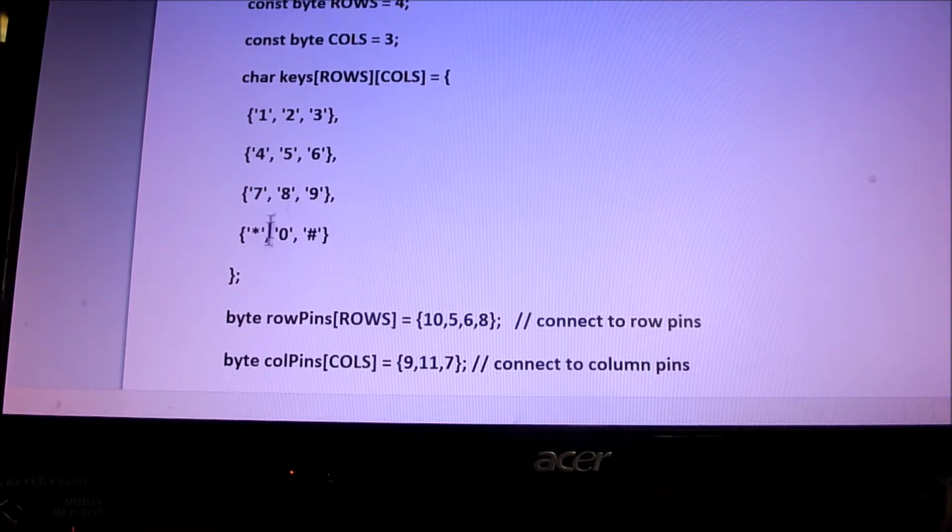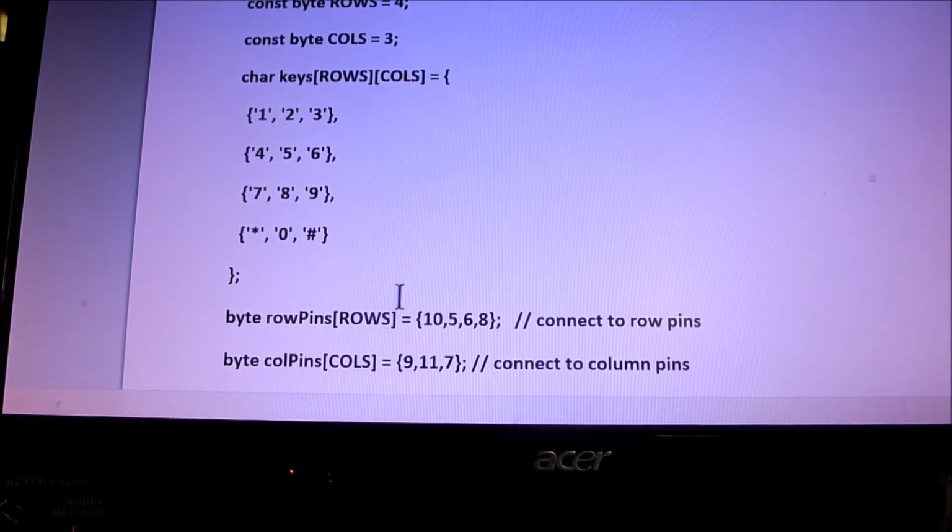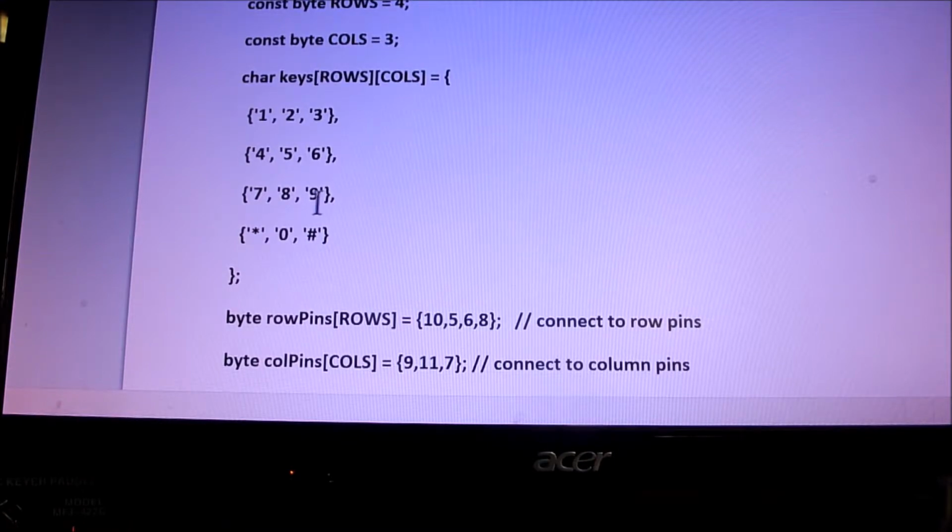We enter it. When we're finished entering it, we hit the # key, and the master says, hey, great, I got a new frequency, and he alerts the slave and sends that new frequency over to the slave. The slave says thanks, and simply relays it on to the GPS, and the GPS resets its output frequency. Pretty cool. And of course the master displays the new frequency on the LCD, and away we go.